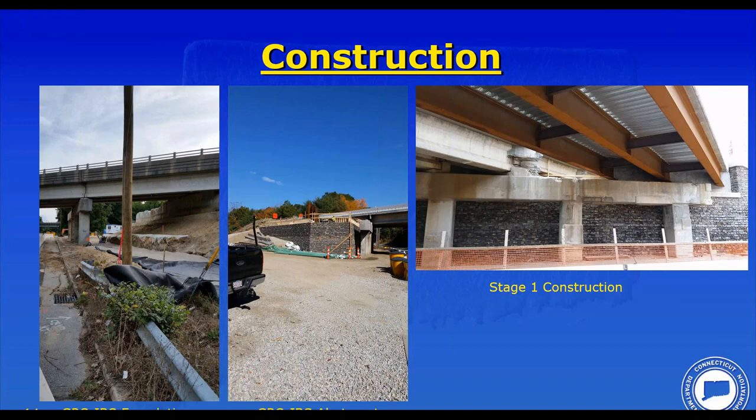The contractor was able to build, and these photos on the left show the beginnings of the GRS IBS footing going in, which is essentially a reinforced soil footing. It's not a concrete footing. That can be done with simple plate compactors. Very easy work, not a lot of big equipment.